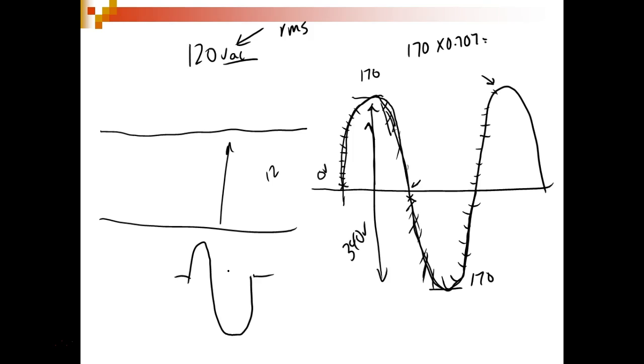So this scope, and this is the advantage of an oscilloscope over a meter: an oscilloscope doesn't average anything. It shows you exactly what's there. And the meter is going to do what? It's going to give you an average, or an effective voltage. On DC, it gives you the average. On AC, it gives you RMS, but it depends on the meter. I don't know if this is a true RMS meter or not.